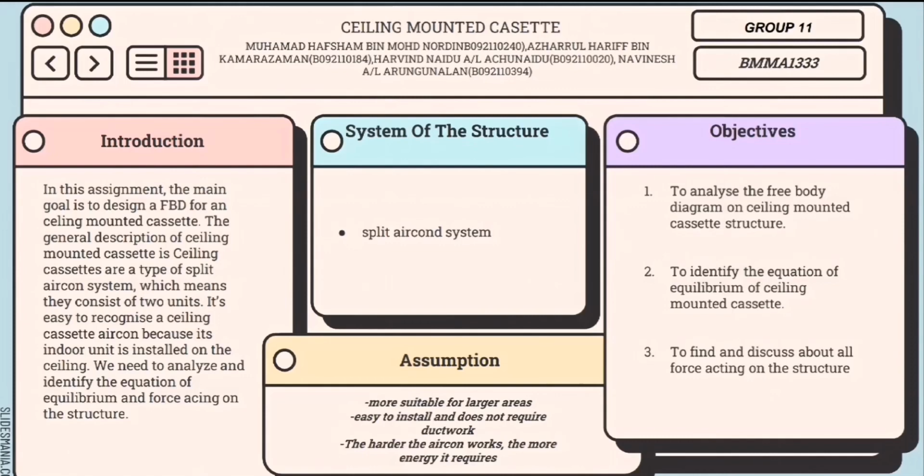Why is equilibrium important in statics? Because equilibrium states a point in which the system will remain naturally as long as there is no disturbance. In mechanical systems, this means that at this state, the equivalent force acting on any part of the system is zero. These states are important for statics because any statics problem exists in a system that is in equilibrium. This allows you to assume the conditions of equilibrium are met, zero equivalent forces, which allows for calculating inner forces in the system.